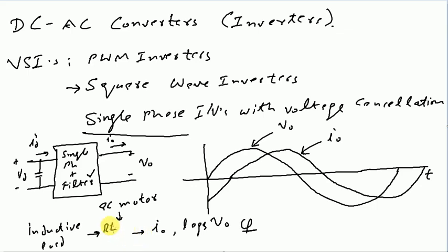If we have a close examination or comparison of these two waveforms, we can say that we have different subintervals. And how do we have these subintervals? Basically, these subintervals represent the combination of polarities that the output signals are having during these intervals. Let me mark them, and that will make it a bit more clear. Now we can see that these different subintervals are labeled, or these boundaries are drawn, with respect to the similarity or the difference of the polarity in the output voltage and current.